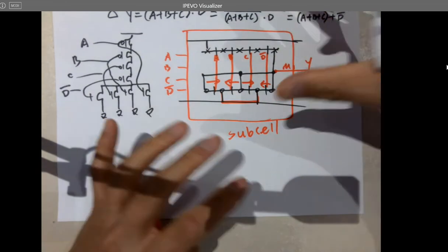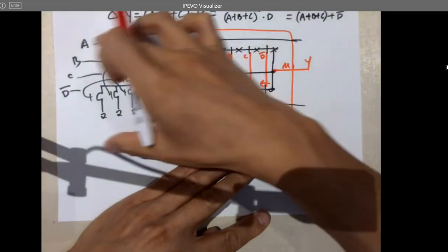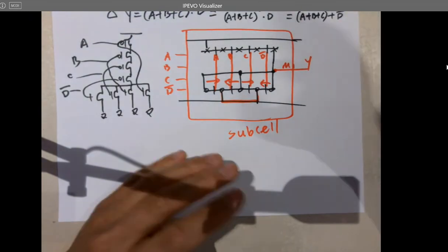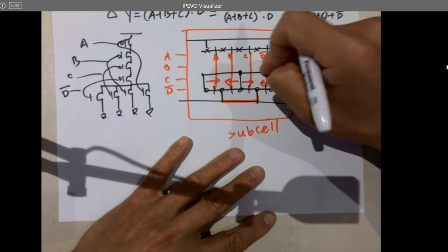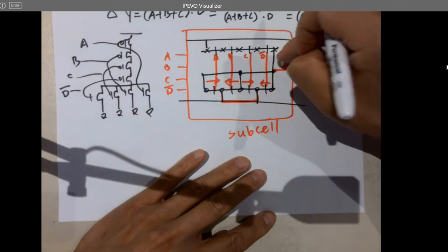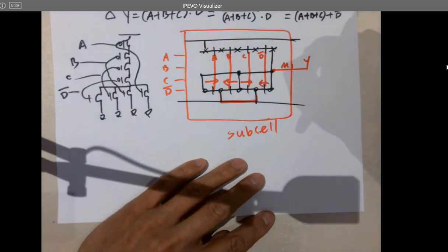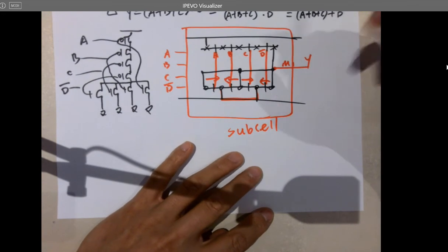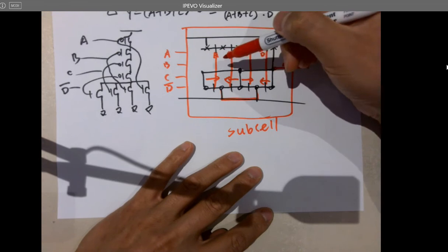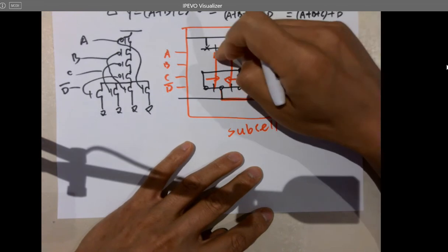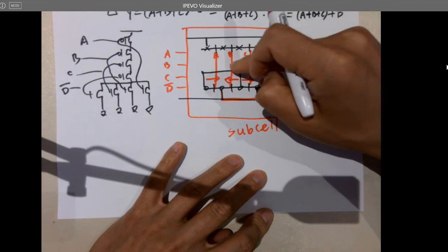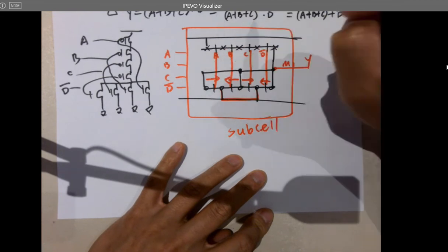That's a physical circuit. It's going to be a layout, not a schematic. It's just representing the circuit connections. But this is a physical layout. It's going to be physically fabricated on the chip. So you cannot make short circuits. So what material do you want to use to connect to the poly? So what are these materials? Polysilicon, right? Gates.